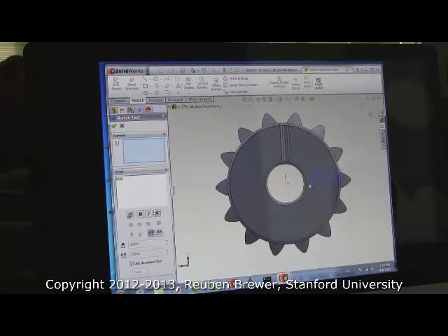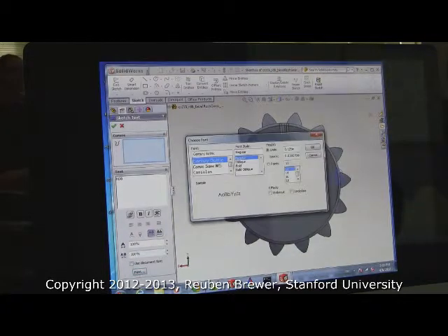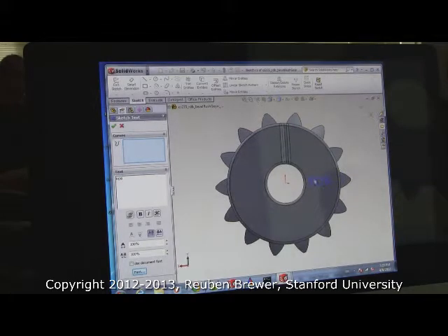But the text is too big for the gear, right? The default text is usually pretty crappy. This little button down here, uncheck that. And check font, and now we're able to make it smaller. So let's do like 0.075. There you go. And I want you to put it roughly center about here. Doesn't have to be precise. Type of cut, just a regular extrude cut.